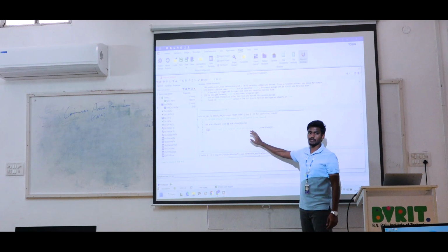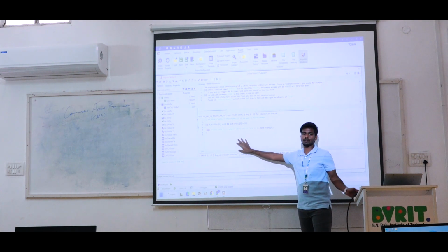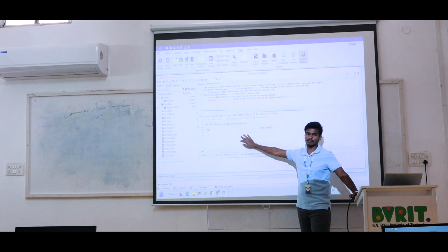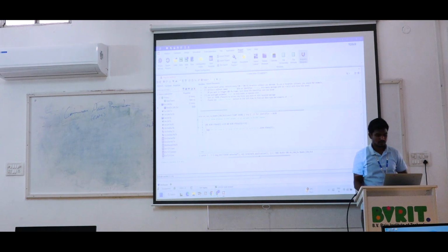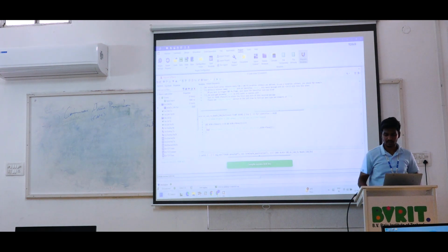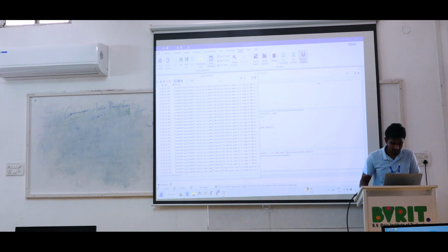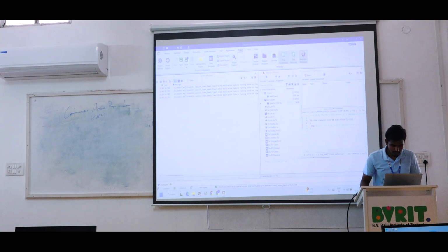Okay. So now one window is transmitting and another window is receiving, but we are receiving by the CAPL scripting and we are checking some condition. The condition is that the vehicle speed range is 100 to 150. Whenever it reaches 100 to 150, we can indicate this with the help of the scripting indicator. Just compile this source, please check whether there is any error or not. After that, you just click the start button. Now the application is connected, go to this message window.